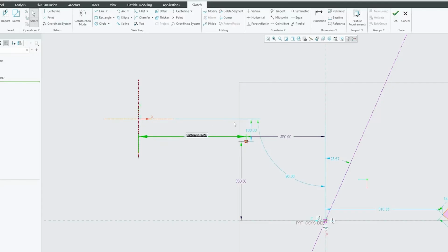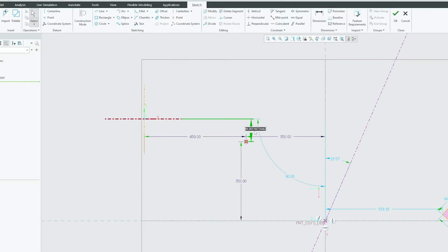Since we are creating this coordinate system inside the sketch environment, and a sketch is generally plotted over a plane, we are seeing the option of providing only two values in terms of x and y. We can also create the coordinate system or even a point outside the sketch, but here we also have an option to create these entities inside the sketch as well.